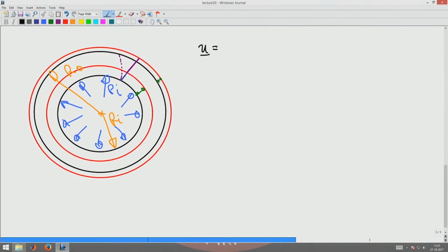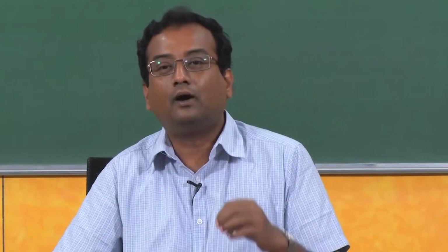So with these observations, now let us estimate or guess what the displacement field u would be in cylindrical coordinates. In cylindrical coordinates there is clearly a radial displacement of the circles. There is a radial component of the displacement field which will vary along the radial location of that point, because we said that the inner circle will not necessarily move the same distance as the outer circle moves. The inner circle can move more, the outer circle can move less, there can be a thickness change. So it depends upon the radial location.